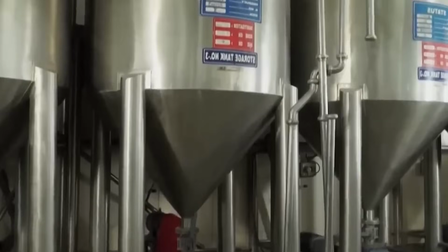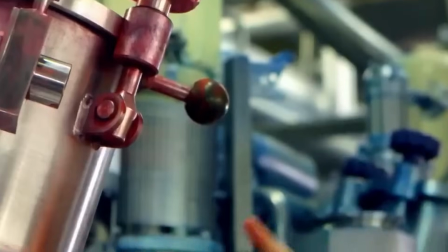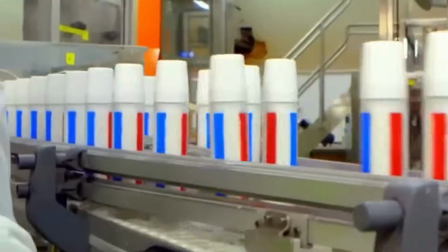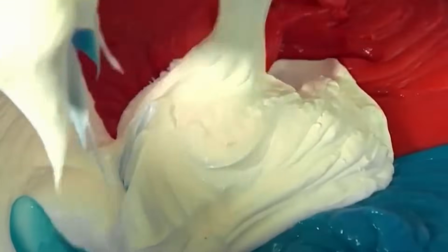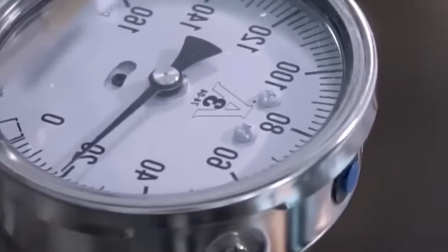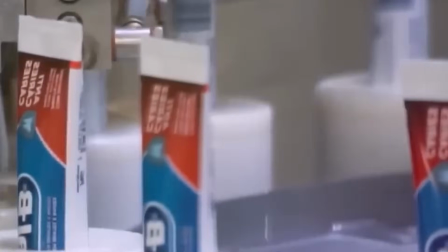Abrasives are typically calcium carbonate, hydrated silica, or dicalcium phosphate dihydrate. These powders are conveyed through enclosed pipelines and loaded into high-shear mixing vessels fitted with load cells. Particle size of abrasives is controlled within 5 to 15 microns for optimal cleaning performance without excessive enamel wear. The feed rate is calibrated by rotary valve controllers.